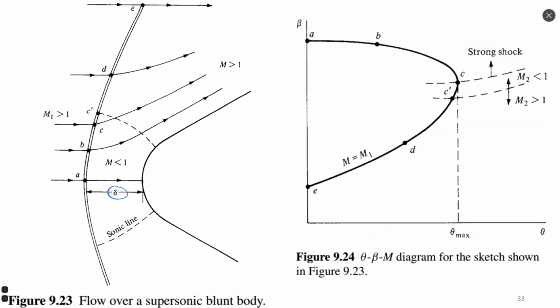Probably, yes. What we can calculate analytically, we can calculate the transition on this bow shock wave in point A. In the supersonic to subsonic transition, we can use the theory of normal shock wave, right? And in other points, you can see point D, the theory of oblique shock wave can be used, right? Because it's already at some theta inclination.